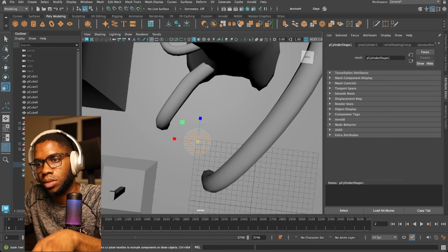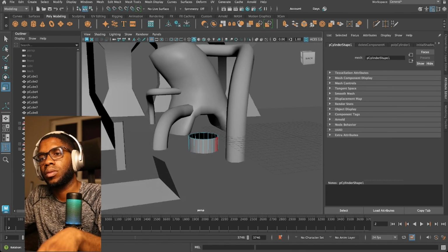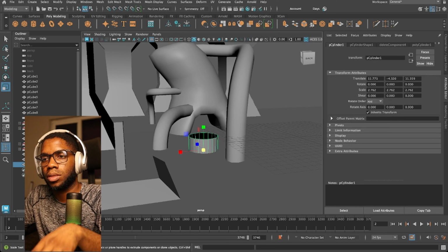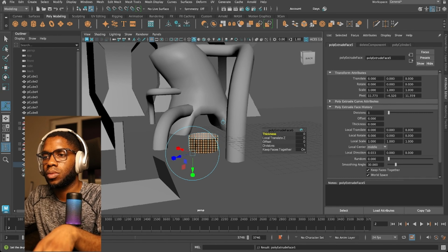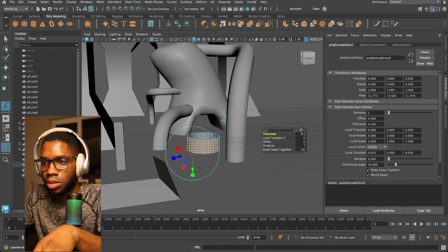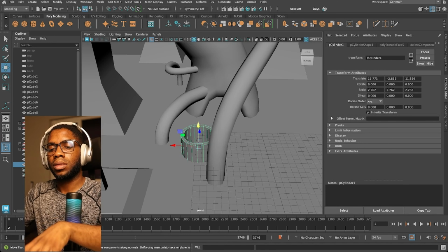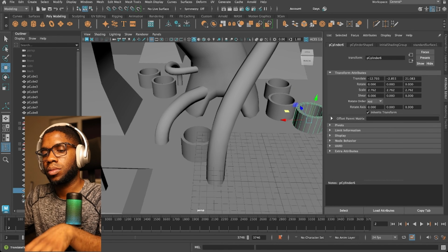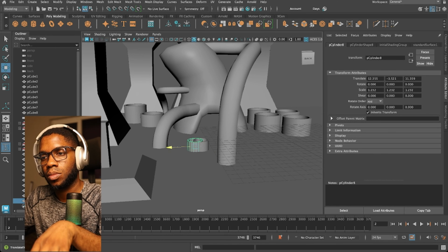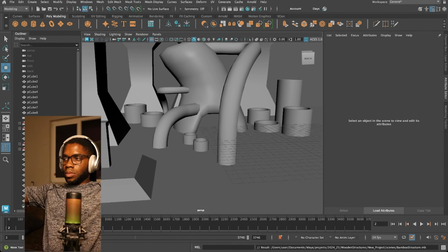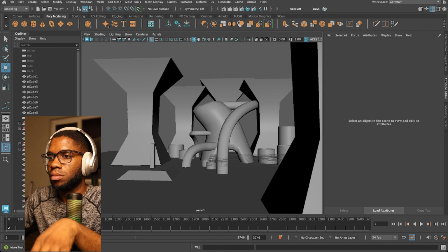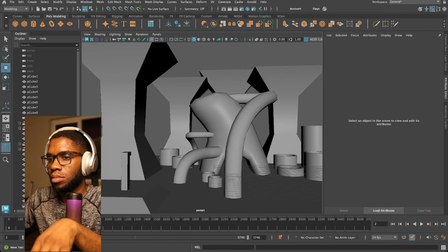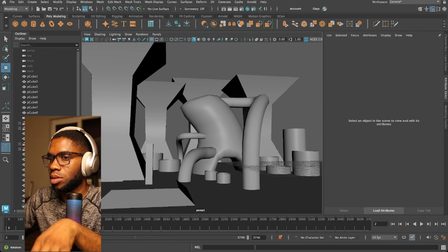Faces, delete those inside. Now we're gonna take these faces. I'm just gonna set object, control extrude. Let's increase the thickness, and there you go. Let's go back to our camera angle, which is perspective 1. Zoom in something like that.